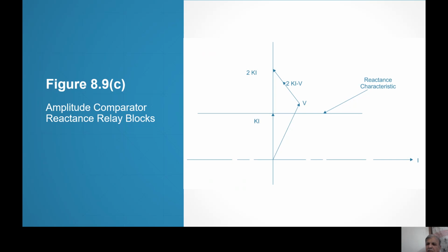Right? So Ki plus V and Ki minus V can be done. 2Ki minus V also can be done because Ki is to be multiplied by 2, or amplified by 2 if I want to talk in static terms, in electronics terms. And 2Ki minus V means subtractor, once again use an op-amp. So all these quantities can be realized, and once having realized, you can feed them.